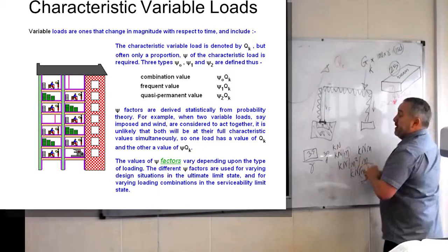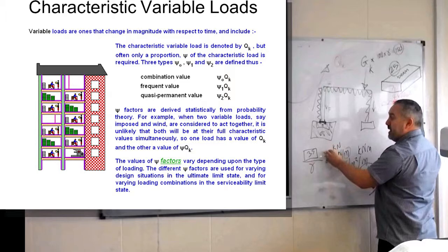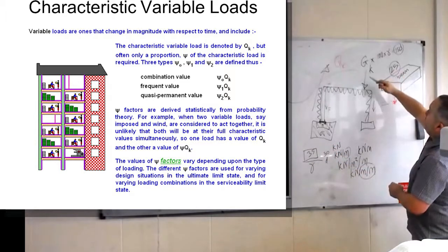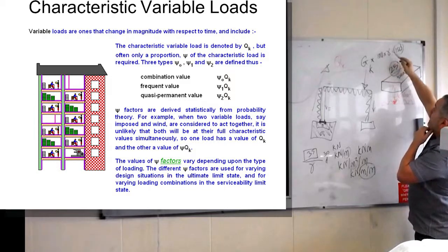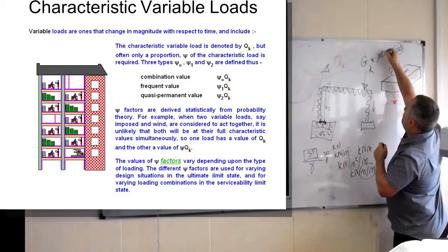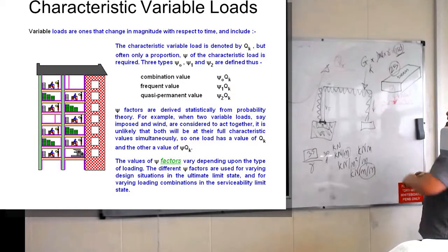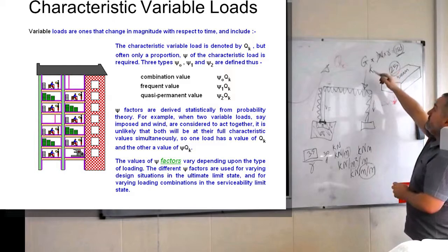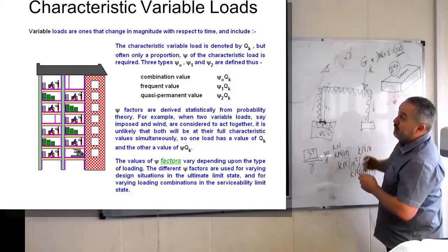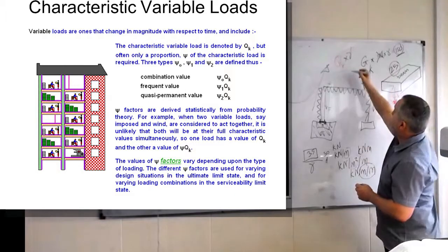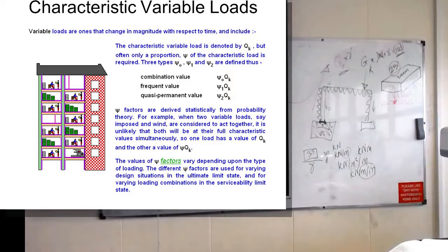So when we have a material, we reduce it by the factor so that we don't rely upon its full strength. And then in terms of our loads that we'd be applying, you'd be multiplying them by a safety factor so that we don't use the 100. We'll be using a much larger value than what we've actually calculated. Now there's those that we multiply by, and you'll find that there unfortunately are a lot of factors for live loads to consider.